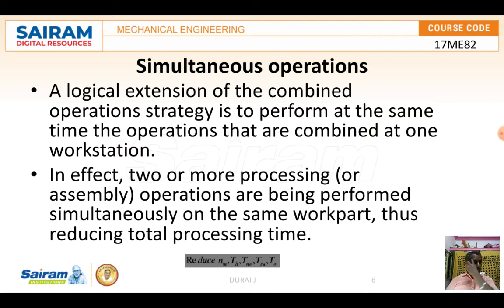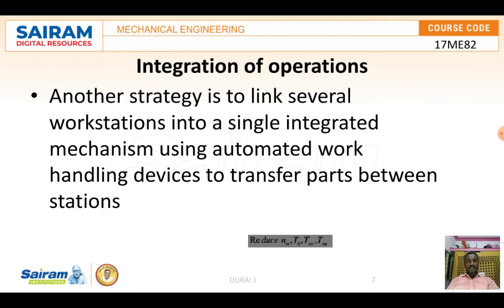Two or more processing operations are performed simultaneously on the same work part, thus reducing the total processing time. Here it reduces the non-operating time, tool handling time, and number of setups, and operation time will also be reduced by using this simultaneous operation strategy.